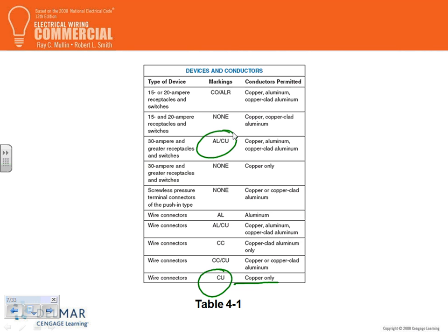So this is what you're going to be, copper or aluminum or a mixture of copper and aluminum. Copper-clad aluminum, guys, I think they have 10% copper and 90% aluminum. Any question, guys, about this? So this becomes an issue with feeders. Almost all equipment, guys, at bigger sizes is rated copper or aluminum, bringing the feeder copper or aluminum. Any question?